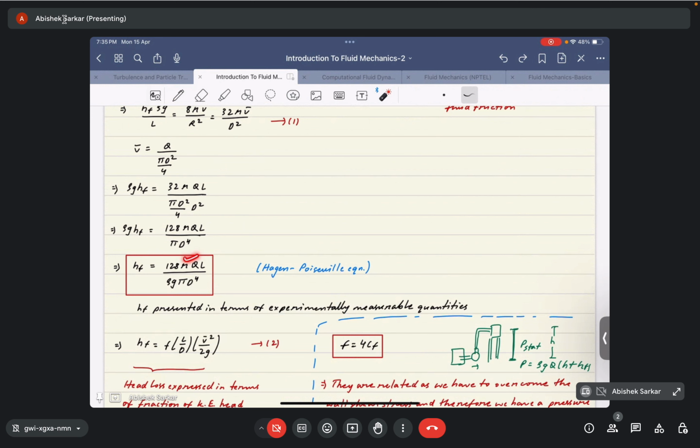is something that is already known in the case of any fluid, pi is again a constant, d is something that is already known for a particular diameter, and q is something that we can usually find by doing certain experiments. Once that is found, we can easily find the value of hf, the head loss in a pipe, from this equation.